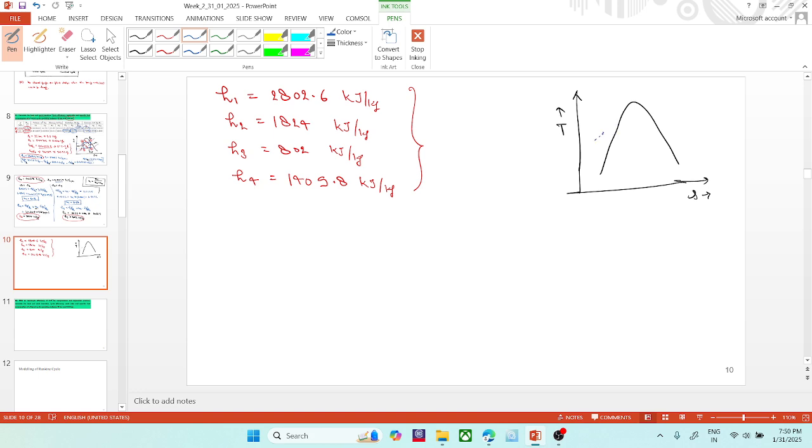My aim is just to make you understand the procedure. So let me draw these two pressure lines and different pressure processes. I have marked point 1 turbine entry, point 2 turbine exit, point 3 condenser exit, and point 4 the pump exit or the boiler entry. So this is turbine work, this is pump work, this is heat in, and this is heat out.